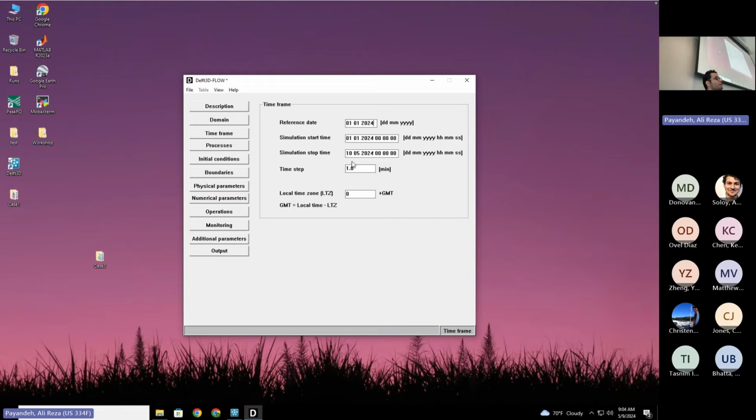In this model, we are going to add the sediment model and sediment fractions. So in addition to the shallow water equations, the advection diffusion equation will be solved for sediment fractions. And the Courant number is more sensitive for the advection diffusion equation. It's better to keep the Courant number below 1 for a model which has sediment or salinity, where the advection diffusion equation will be solved.